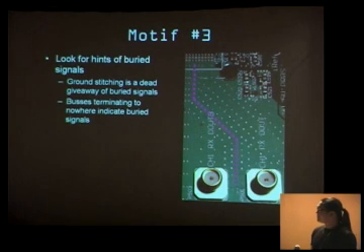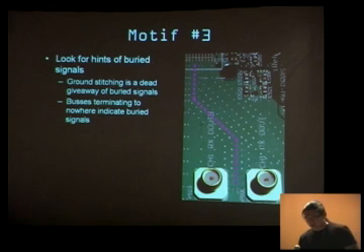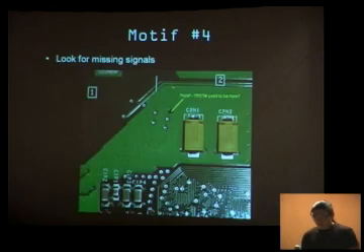You can see this pattern of stitched vias along here. And I drew this pink line. It turns out there is a very high-speed trace right along here going to these two connectors. And so you can actually look for the gap between these ground vias. You can know there's a trace underneath it because they're trying to build an impedance-controlled box for those traces. So I didn't have to peel the board back or even get to an X-ray machine. I know these pins are connected to this. I don't even have to pull out a meter or anything like that. So that's oftentimes a motif to look for.